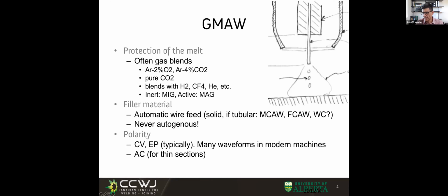One interesting difference with TIG is that if you remember, in TIG we run at constant current. So we would have always the same intensity of the arc. But in MIG we run at constant voltage. How interesting. So you might wonder, hey, didn't I want to keep the same intensity of the arc? And the answer is, yeah, of course you'd like to keep the same intensity of the arc. But there is something more important in MIG.